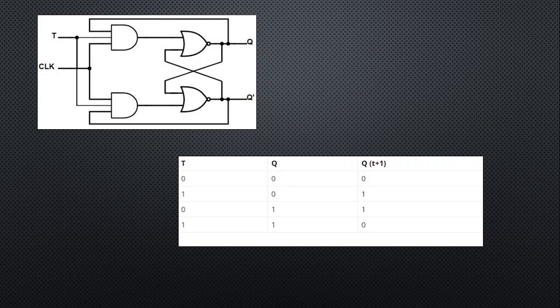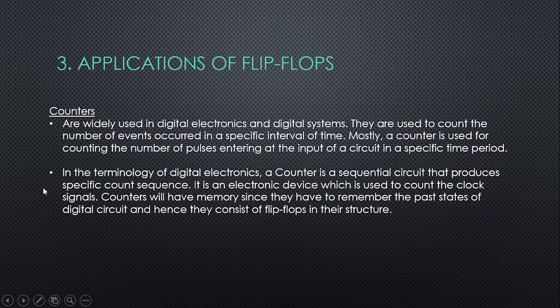So we have here Q is 1. Meanwhile, Q prime operates opposite. When T is becoming low, 0, the output remains the same, it's latched. So what happens if we move to logic 1 for T again? As you can see, for Q, it latches and remains the same, and for the Q bar, this is the time to toggle. So they just basically toggle each other based on the status of this T, whether it's high or low. So that's all for the four types of flip-flops.